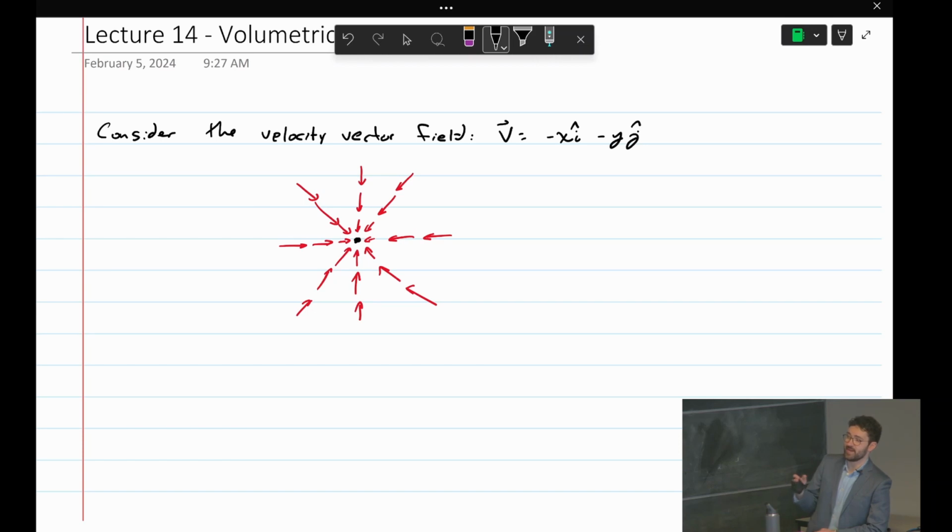That's good. If we had a z direction, you could say, okay, maybe they all come to a point, but then they go straight out. It's like a very weird vector field. But if we don't have a z component, this doesn't really make sense, right? Like Aaron said, the velocity all just comes to a point, but where does all the fluid that was transported to that point go? In fact, we'll show later on that this isn't a valid flow field for an incompressible fluid.